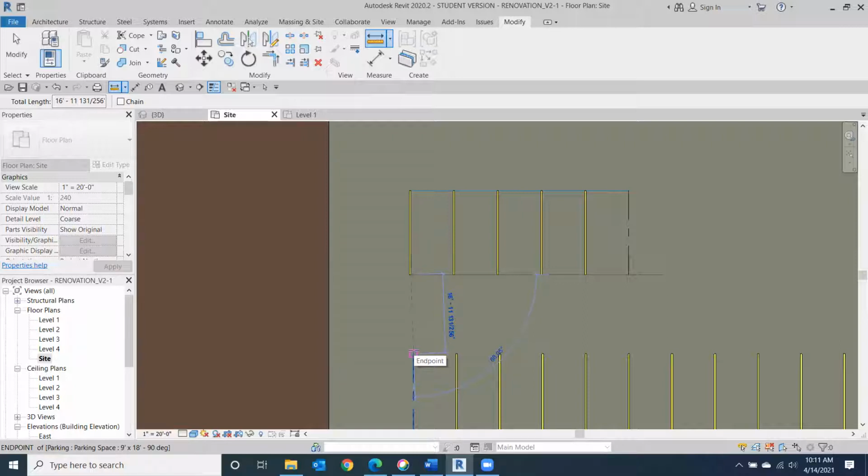But one thing you want to think about is what the distance is between these two spaces, because we'll have cars going down this way, we'll have cars going down this way. So if you want to space those at least probably 16 feet apart, 20 feet apart, whatever, you just want to make sure that they're not so close together that it's hard for somebody. Think about the traffic flow between these two spaces when you're laying that out.